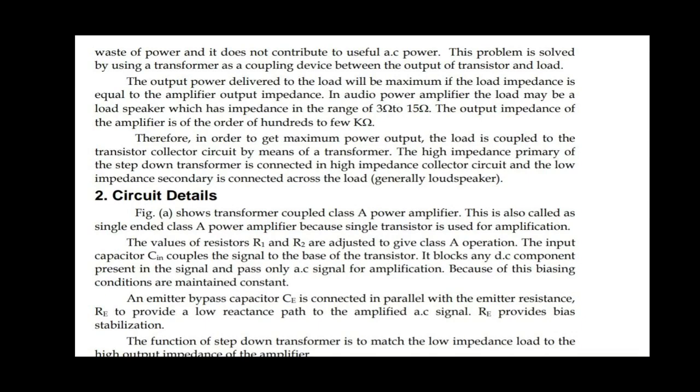The function of the step-down transformer is to match the low impedance load to the collector. The values of R1 and R2 are adjusted to give class A operation.